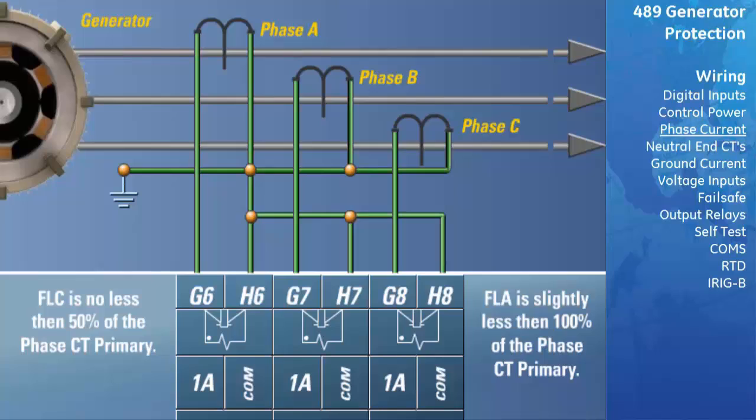The maximum phase CT primary current is 50,000 amps. The relay will measure correctly up to 20 times the phase current nominal rating. Since the conversion range is large, 1 amp or 5 amp CT secondaries must be specified at the time of order such that the appropriate interposing CT may be installed in the unit. CTs chosen must be capable of driving the relay phase CT burden.